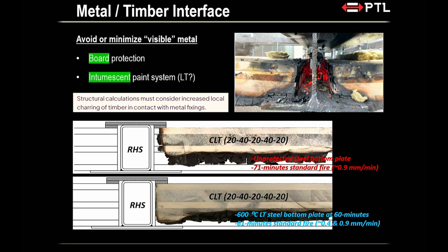It's definitely just from the underside. Yeah, the fire is from the underside. How about the intumescent? Or is it the whole? Sorry. The intumescent paint is just on the steel plate. Just on the steel plate. Not around the RHS or that above. What about when they say, well, intumescent paint won't work because it's got a timber hard up against it?